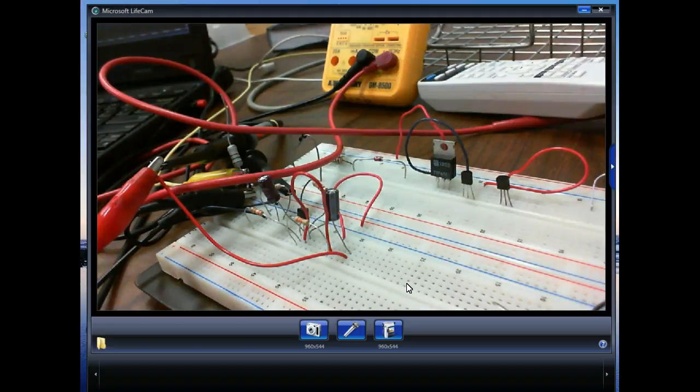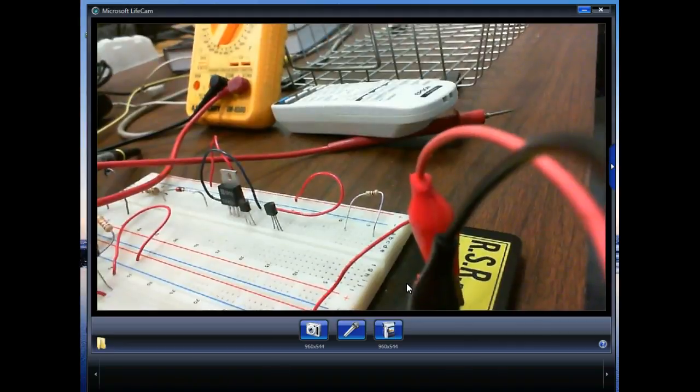But remember the voltage gain on this one. What's the voltage gain on the common collector amplifier? Yeah, it's about 1. In fact, it's slightly less than 1. We're powering up on 10 volts. If we bias this correctly, pretty close to the center, we could put almost a 10 volt peak to peak in there. So where it says 1 volt peak to peak, we'll put something that makes it easy to measure on the oscilloscope. So right now I'm putting in, let's go ahead and do it.